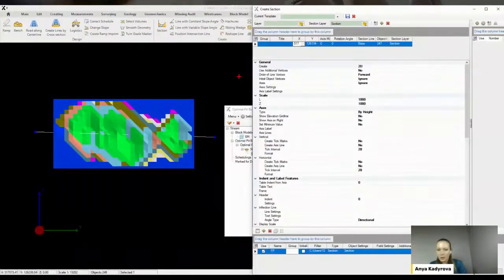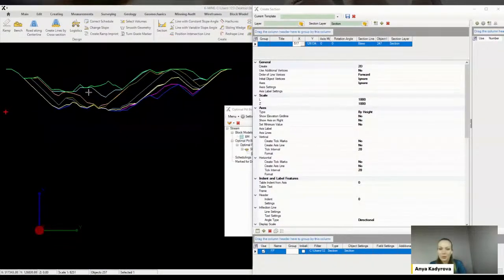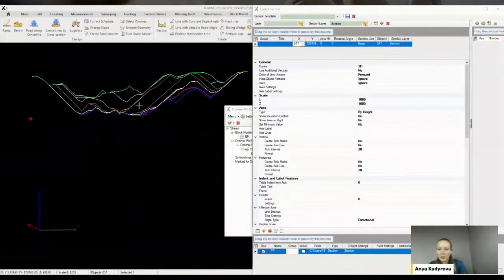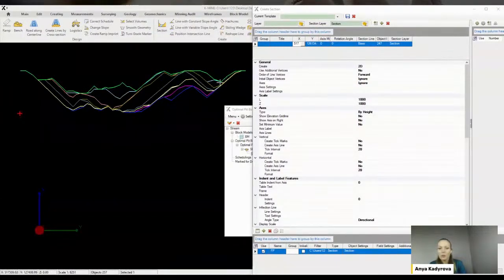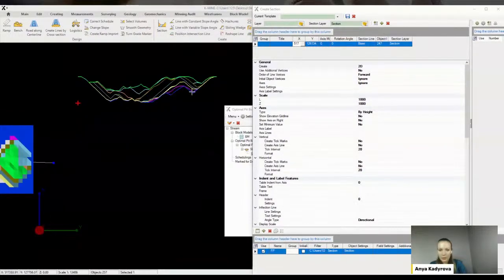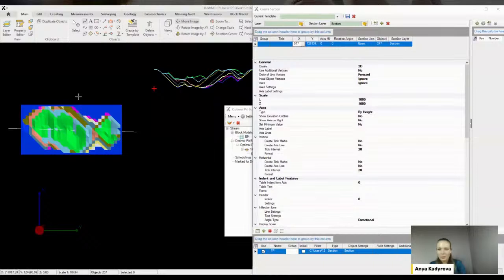We can see that the longitudinal section shows significant changes between price adjustment wireframes, and the farther to the east, the more significant it is. From this, we can conclude that the price of the final product significantly affects the final contours, and the choice of the optimal one must be treated with a margin, so we would leave reserved lands on the surface around the pit, since the pit can significantly expand if the price of the final product rises.